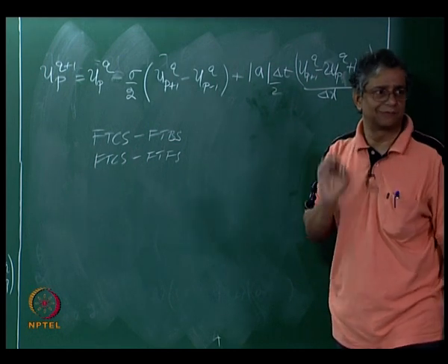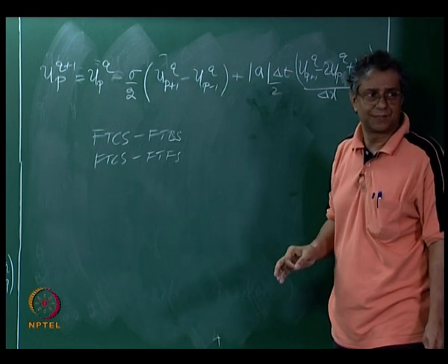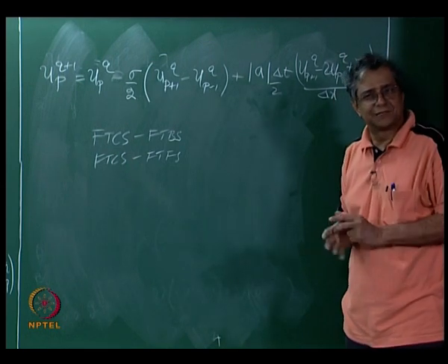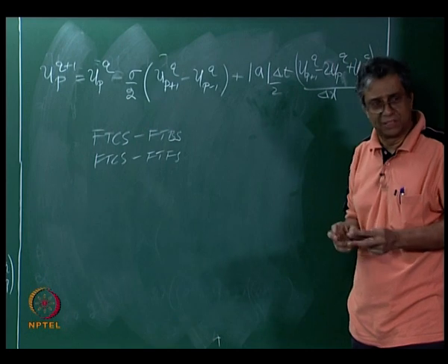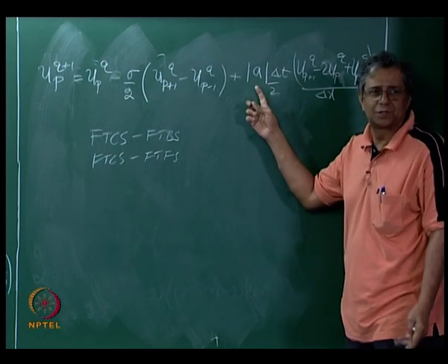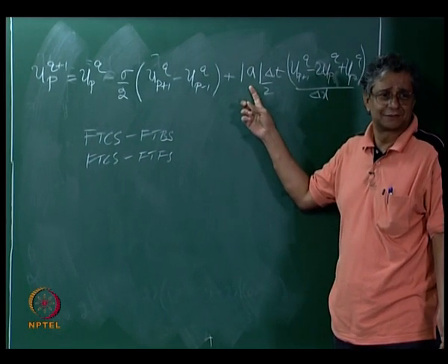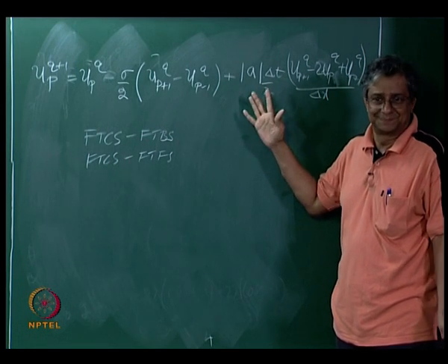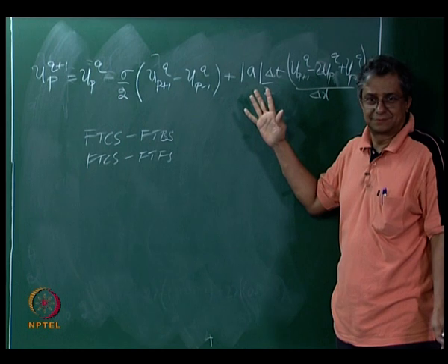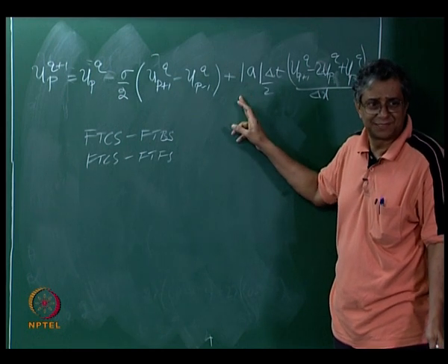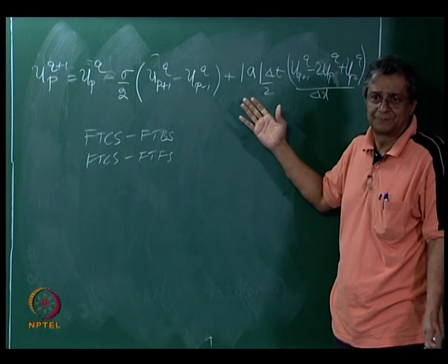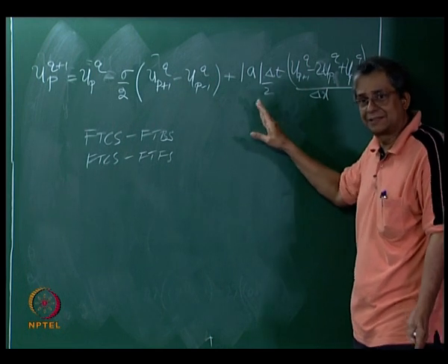You add the right kind of artificial dissipation, right, you add the right kind of artificial dissipation. Of course, from a stability point of view, what we are talking about earlier, I can't afford to have this A to be negative, that is pretty obvious, that is mu2 negative, right, that is mu2 negative. Does that make sense? That is mu2, if A is negative, that means mu2 is negative, it is going to diverge, right. So it is pretty clear that it has to be modulus A.